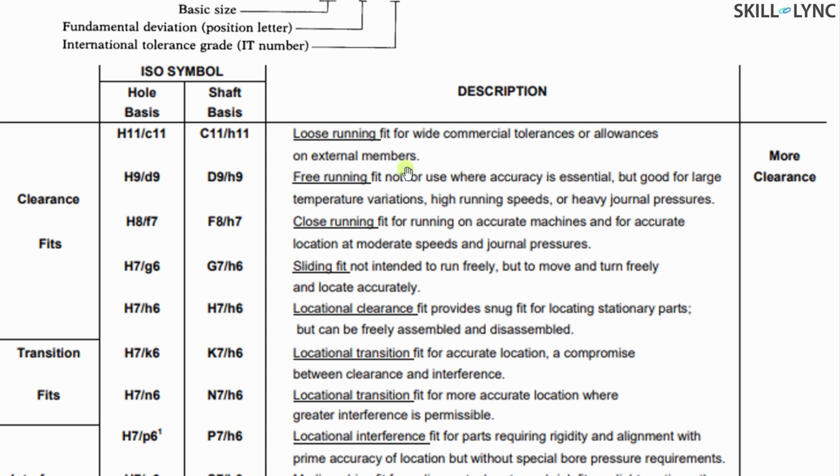That is, there's not going to be any interaction between the components together. It's just a loose fit component between those two, shaft and hole. So then you can go for this referencing. Next, for this, it's called a free running fit.